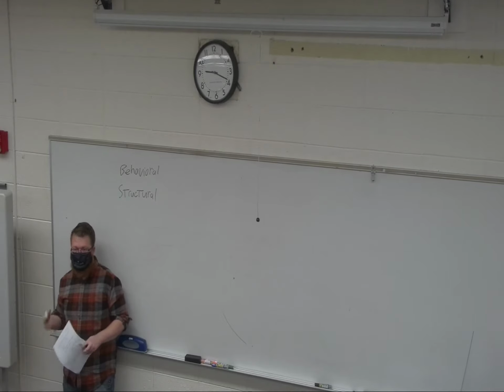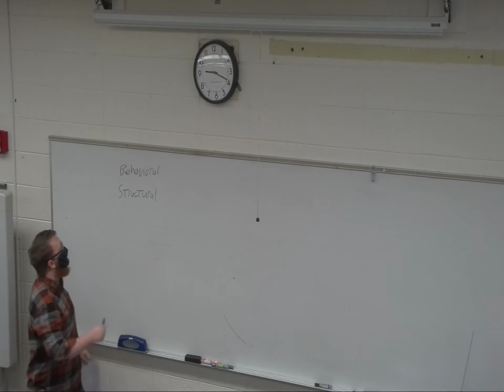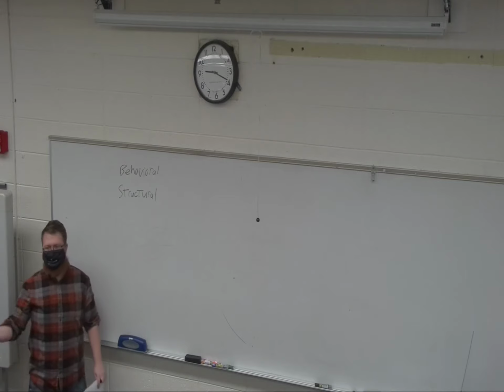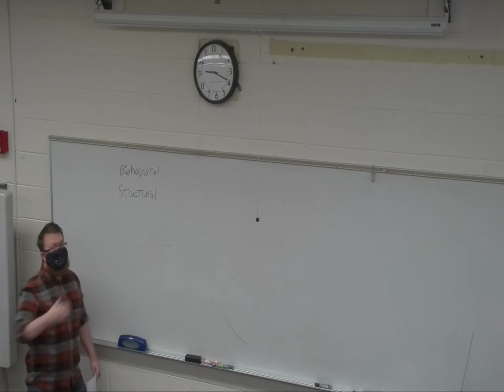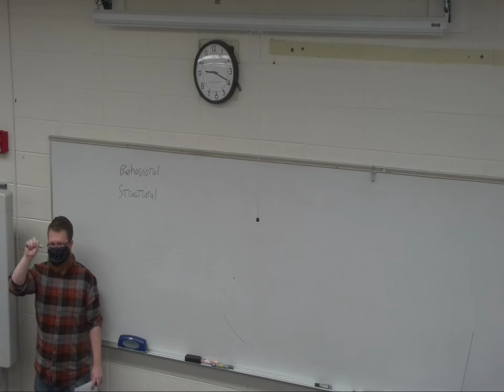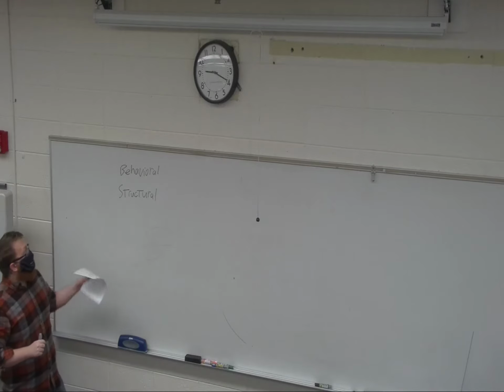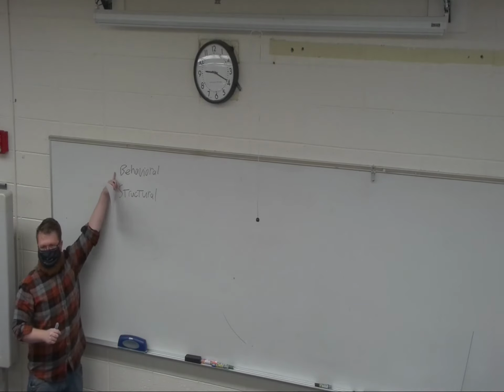So behavioral is what it sounds like. You're describing the behavior of it using a hardware description language. Structure is you're describing the structure of it. So behavior is going to include things like mathematical expressions for logic, whereas structure is going to be used for, like, I want this gate connected to this gate in this particular way, right? This and that and this, so on and so forth. Most of what we write is in behavioral.